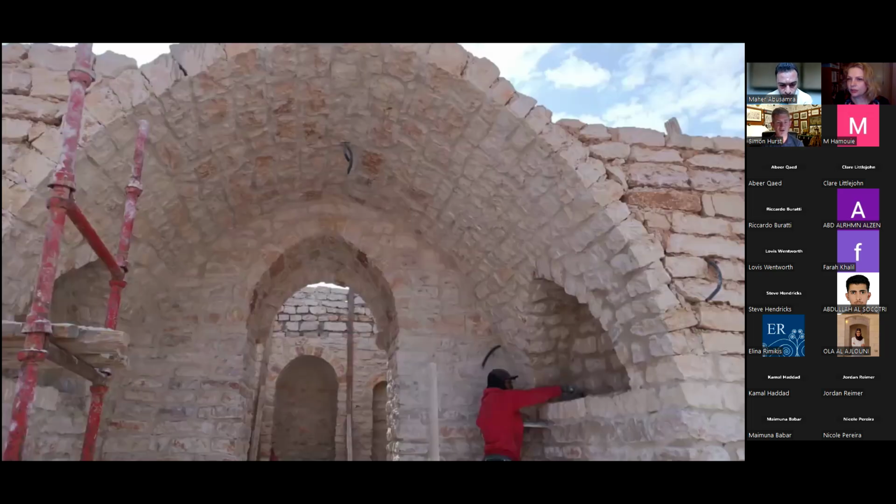I was going back to your structural thing. You used three-centered arches, a lot of traditional ones. You also used catenary arches, I noticed in one project, which reminded me of Gaudi and his models using chains and little weights. He hung them, and then you build the reverse, and it automatically stands up because all the loads transfer. But my question was more about the setting out of the arch. A catenary arch is not so easy to set out on site with shuttering, because you're not just using a radius and rotating it. So is that a more complicated thing to do on site, or how do you do that?